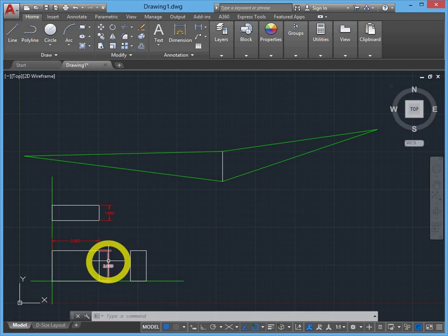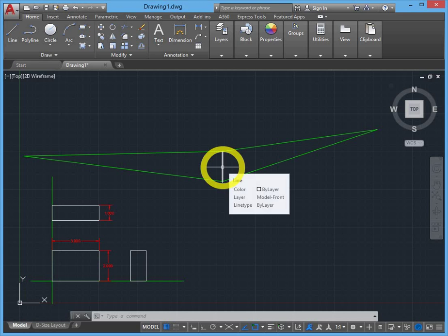Now the rest of the features on the object, in the width direction along these construction lines, will be true size but not true shape. In the depth direction, they will be true size but not true shape. This central line right here, which is the intersection between front view and right side view, is the single only feature in the entire drawing that is true size and true shape vertically.